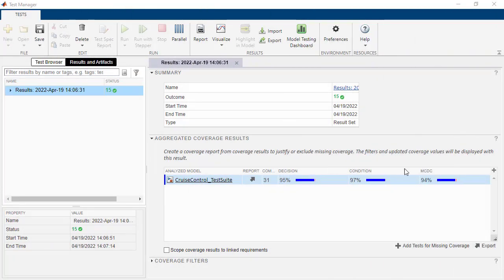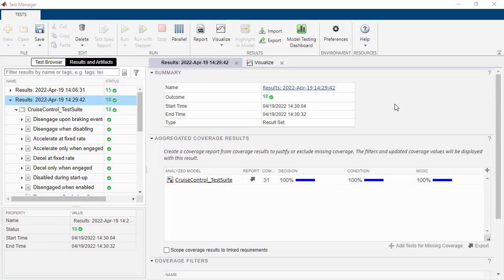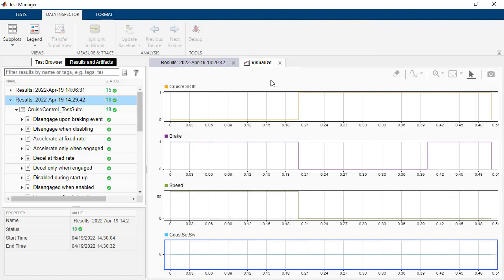You can also use Simulink Design Verifier to automatically generate test vectors. You can simulate these test vectors to understand how to achieve full MCDC.